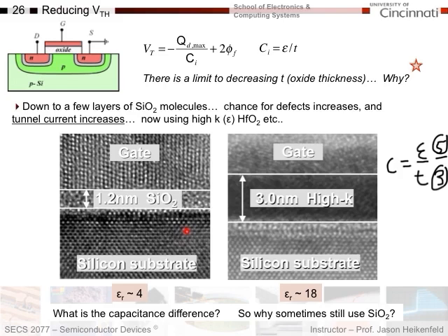And so the key point is that if you want to make a perfect layer, that's easy to do with silicon dioxide because you start with this perfect silicon substrate, and all you've got to do is basically rust it. You put it in the presence of some oxygen or water, and you get this nice little perfect thin oxide layer to grow into the surface.